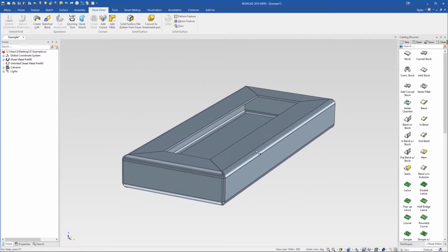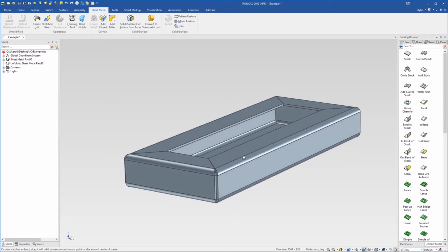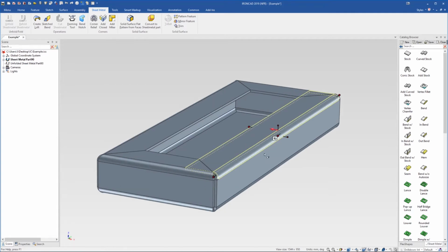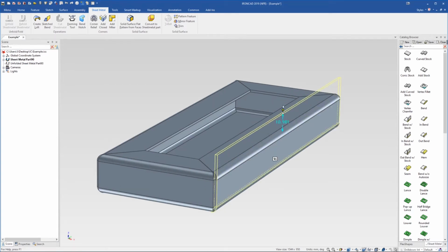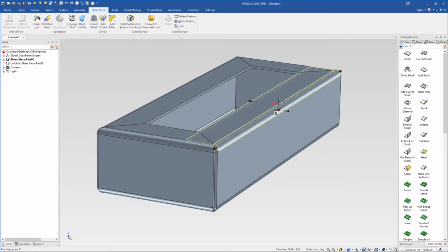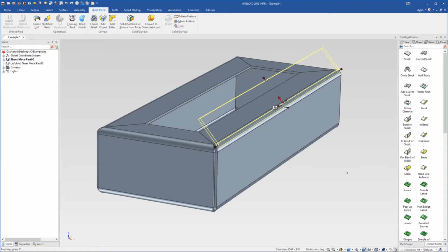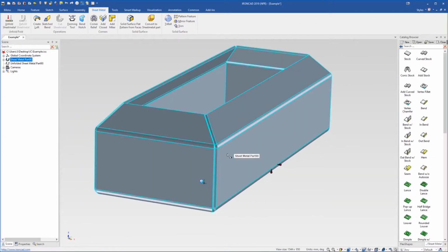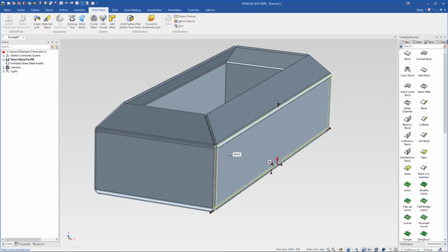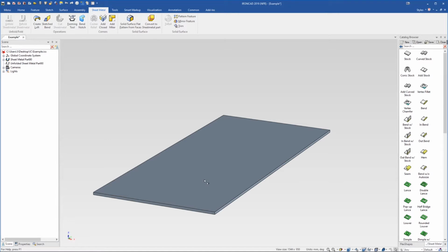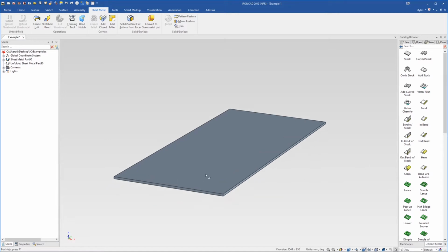When you have created a mitered box like this, you can actually go in and edit the bends themselves on the original part of the mitre, and it'll update the rest for you as well. So for example, if we stretch this up, the rest of the box will update. Or if we change the angle, the same thing. Now I'll delete this and go into more detail about how the sheet metal parts themselves work and how to change the angle and things like that, which we just did there.